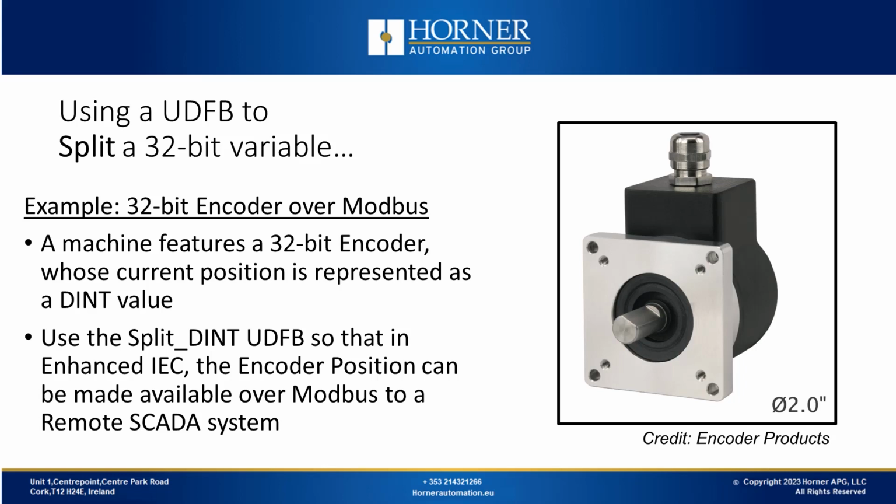Modbus really only supports single integers. So what will we do here? We're going to use one of those user-defined function blocks so that we can split that double integer variable into separate integer components so that it can be seamlessly read by the SCADA package.